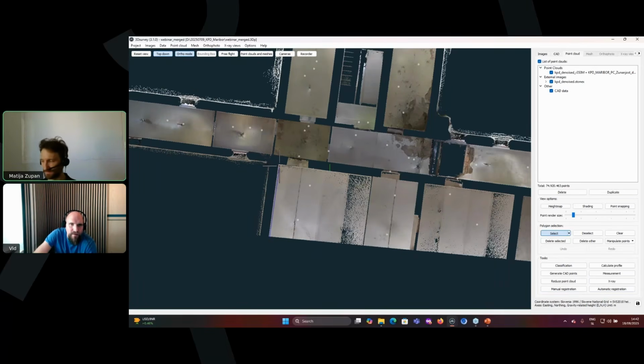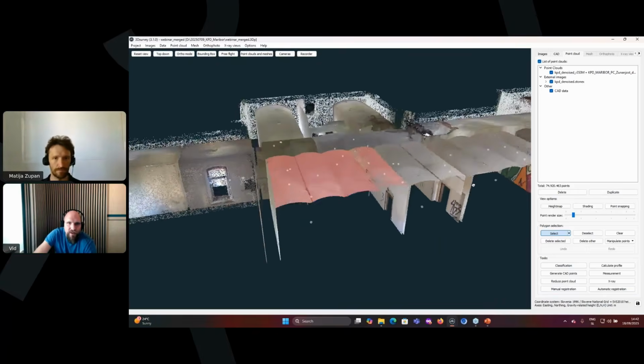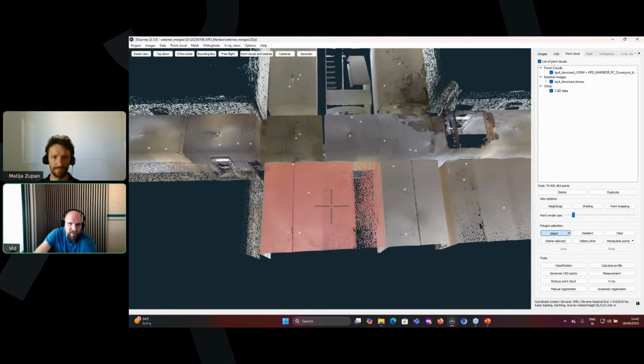Within the ceiling. Yeah. So without the wall section, like that. Now I go out of top-down and ortho. So now we want to know the average elevation here. We'll use this trick: manipulate points, average height.